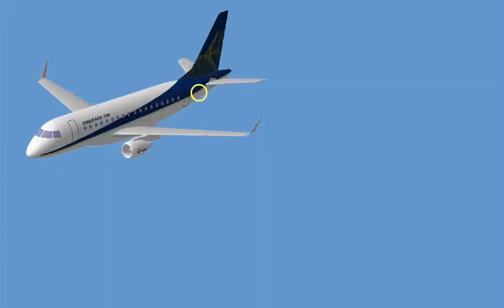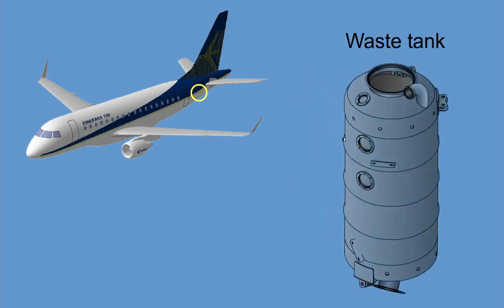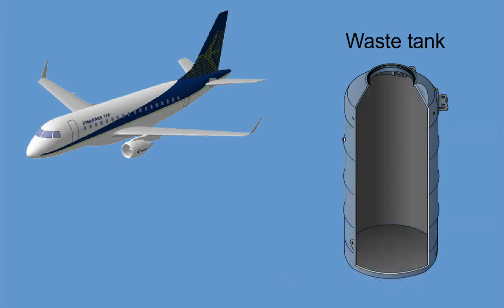The waste holding tank is mounted between the aft left lavatory and the pressure bulkhead above the floor level. The usable capacity is 25 gallons, 95 liters. Brackets welded to the side of the waste tank wall are used to mount the tank to the aircraft with adjustable tie rods. The thin-walled stainless steel tank is completely sealed on the inside and will resist the impact loads caused by heavy solid objects that may be flushed into the waste system. The tank can withstand a pressure of 50 psig, or a vacuum of minus 12.6 psig.